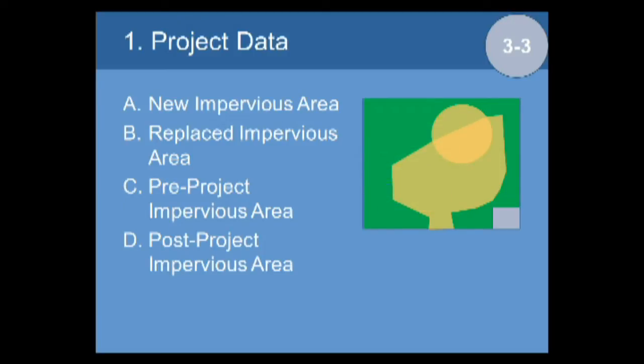And then if they're now obviously building over part of it and demolishing the rest of some of that existing, then when they end up here, but they're leaving this, that's the post-project impervious area. So it's pretty clear once you see it visually and think it through, but a lot of folks get it wrong, and I think if you're a municipal reviewer, you're going to end up having to explain this a few times. That net idea can actually now simply be shown by doing the algebra: it's the new plus the replaced minus the amount that you reduced the impervious area on site.